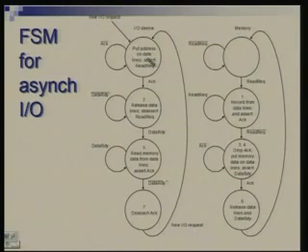In this state, the requesting device is putting the address on the data lines and asserts the read request signal. On the other hand, memory is in this state waiting for read request to become 1. While read request is 0, it keeps on cycling in this state.